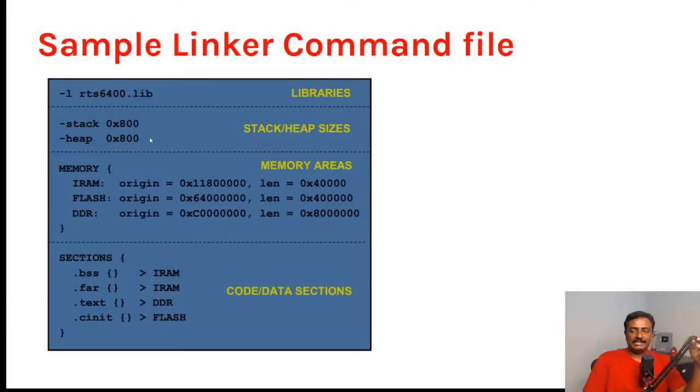No, the stack size and heap size. This answer is for Sandeep. Okay, nice, Sandeep. The stack size and heap size depend upon the local variables. For example, if you take image data and you have a lot of coefficients, in that case you have to increase the stack and the heap size. It depends upon the application. Okay, is that clear? Just type clear in the chat box. If you want me to repeat, just type repeat in the chat box.